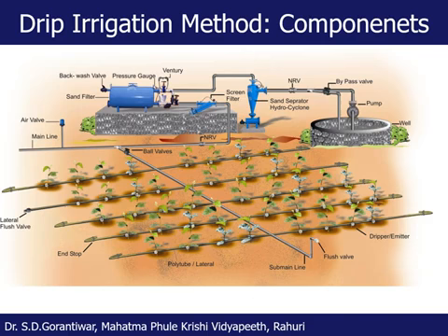Okay, by chance, if impure water enters the system, then there is possibility, not possibility, there is 100% guarantee that the emitters or drippers will be clogged, because they have very small apertures. If sand particles or clay particles or certain debris enter the system, debris will of course block the pipe network as well, but these clay particles or sand particles will also block the emitters,